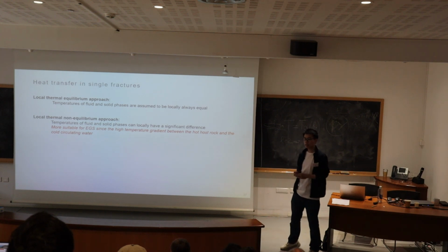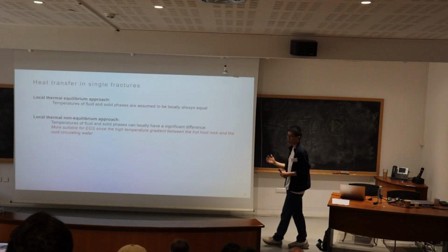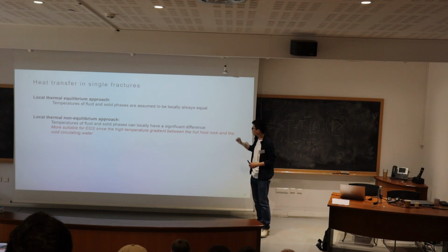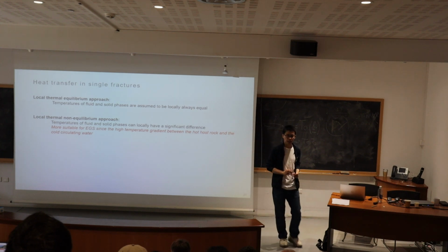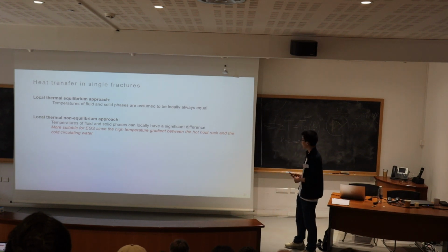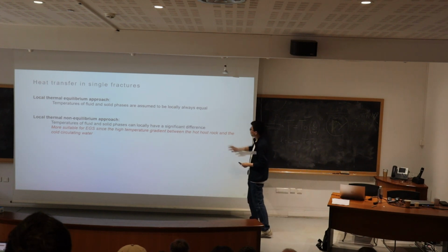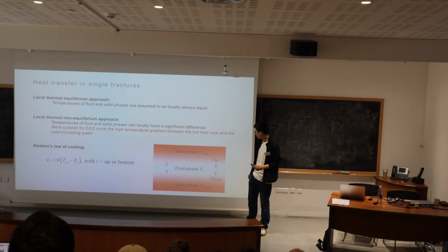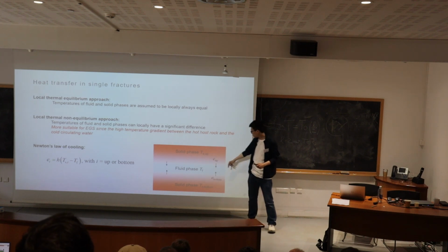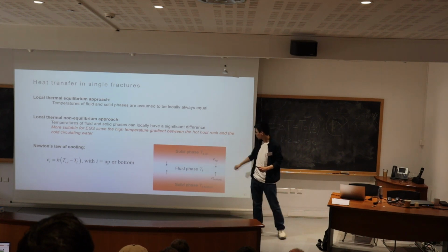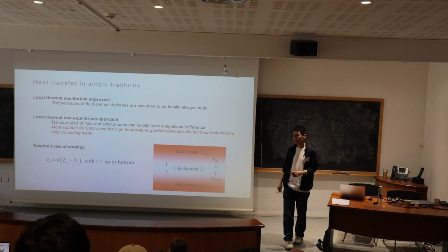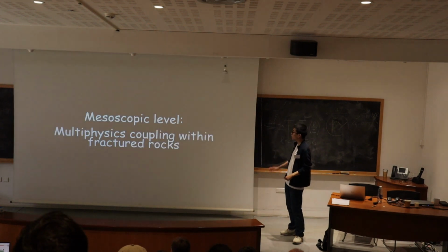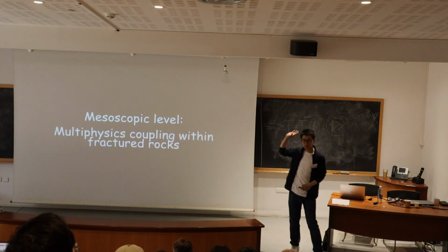But this may not be directly applicable for EGS problems, because in EGS we often have a high temperature gradient, so we may not always have instantaneous equilibrium. In this case, we can use Newton's law of cooling to consider the energy flux from the solid phase to the fluid phase through the fracture. So these are some fundamentals.